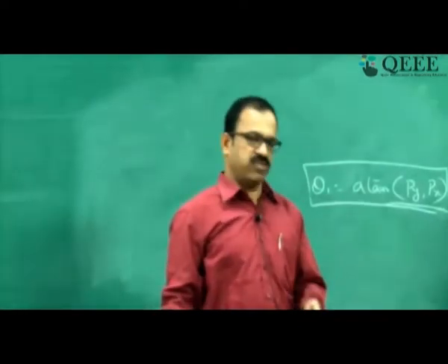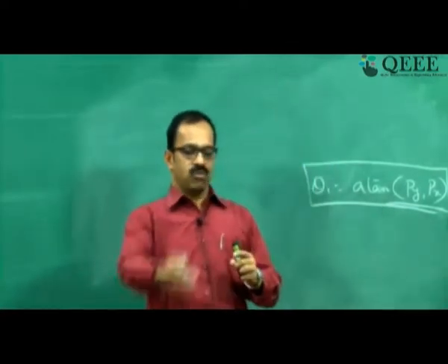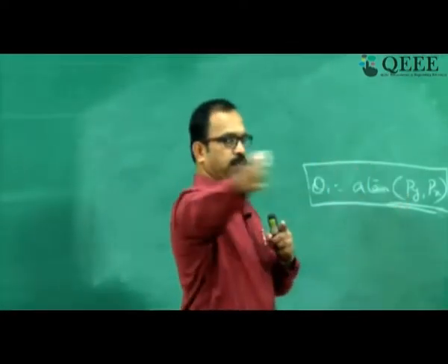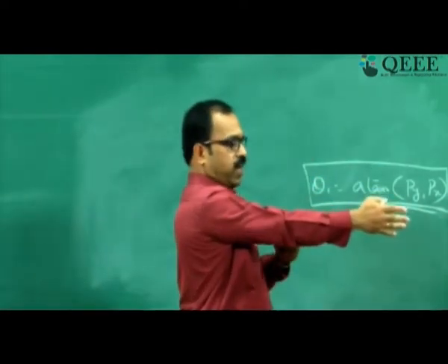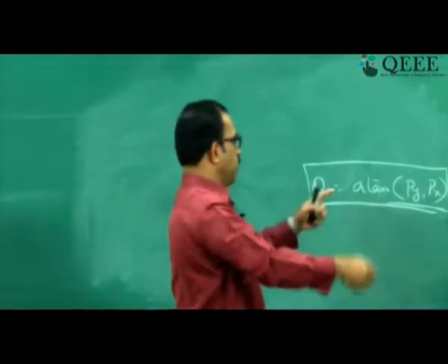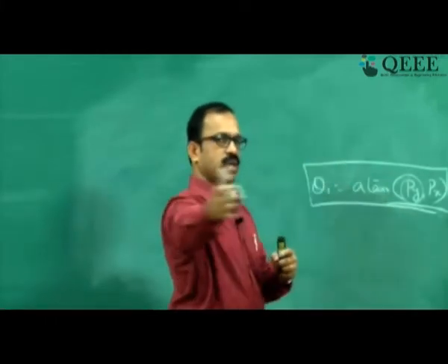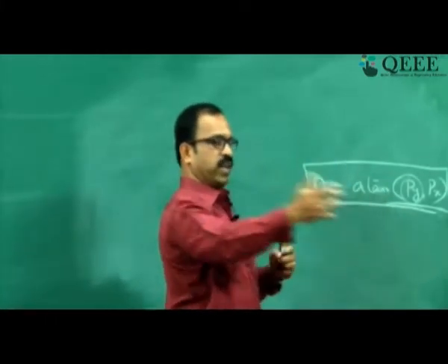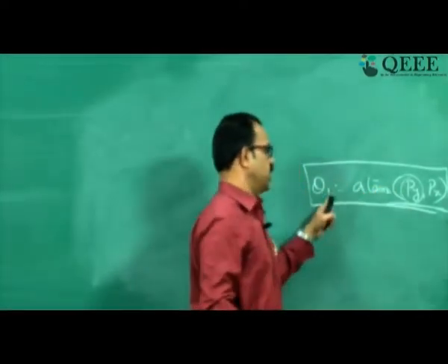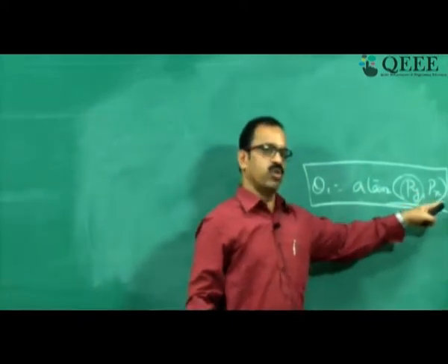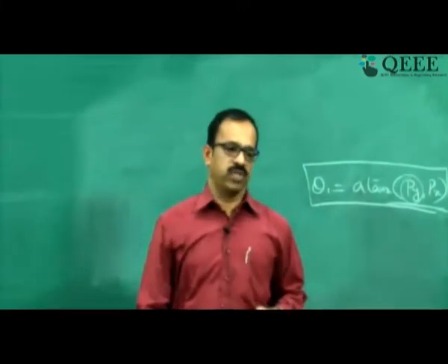Now if you go back to the previous diagram, you can see that theta 1 is about the vertical axis. If this is the plane, anything going out of the plane is theta 1, and theta 2 is in this direction. It is very clear that the y coordinate is always decided by theta 1, because it is going out of the xz plane. You can easily find theta 1 if you know the y coordinate and x coordinate to be reached. So the first joint angle can be easily solved, and you got theta 1.